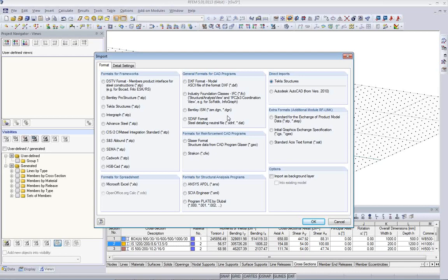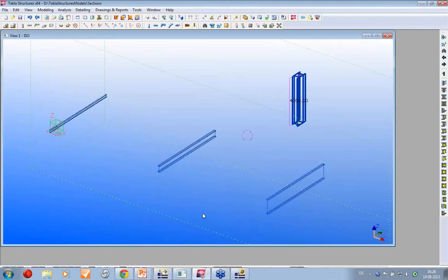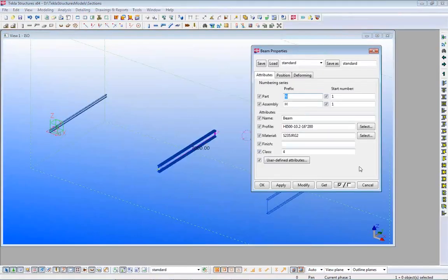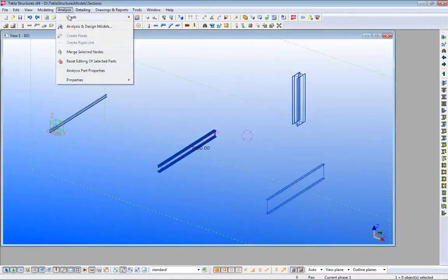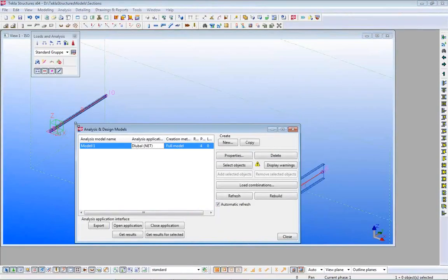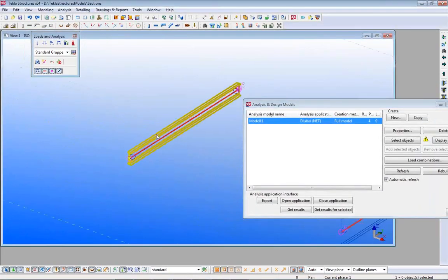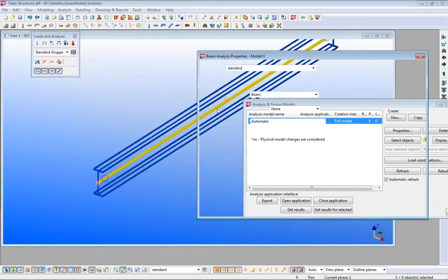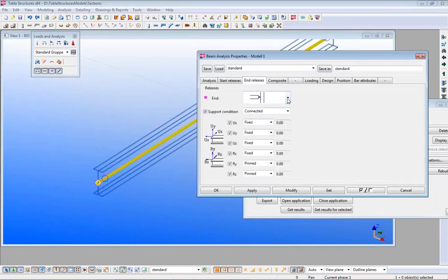Can I use springs as a release in Tekla? As I said, in Tekla, you need to have an analysis model. You can set up releases here and also spring constants. They can be, for example, a spring. And if you have this spring constant, then we also import this spring constant inside our analytical model.